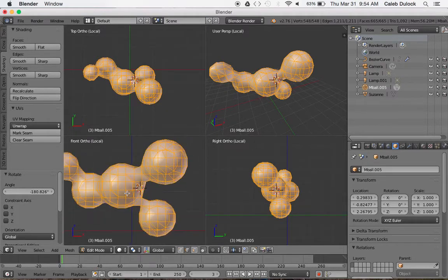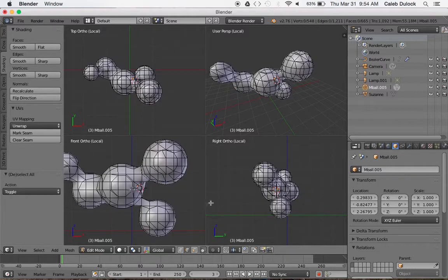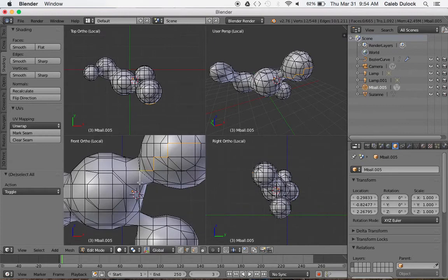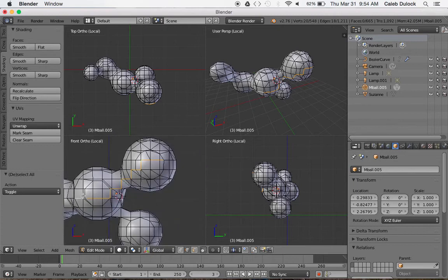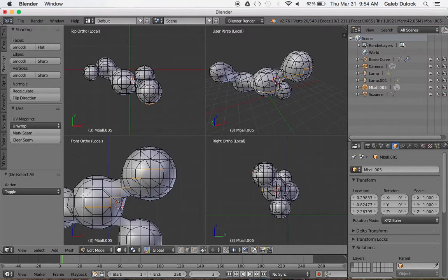So I'm going to zoom in, deselect everything, use my edge selection from the base, and I'm just going to grab a collection of connected edges. I'm not going to create any special shapes for this particular seam. Even though you can create independent shapes with seams, you can actually cut out entire sections with them.